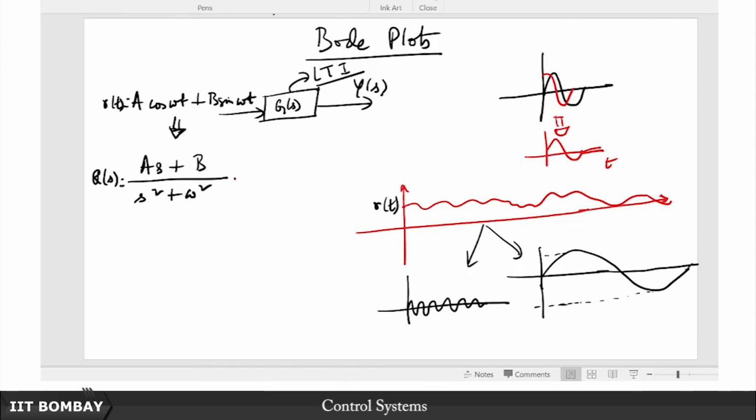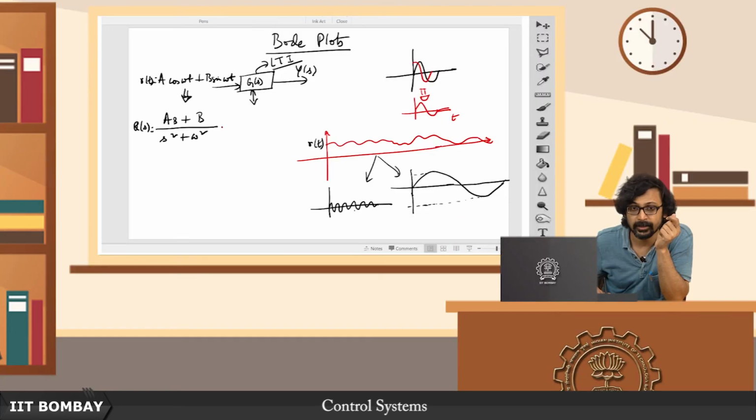So this is the frequency domain response, the frequency response. In every possible frequency that we might be interested in, how does this particular LTI system act on signals of different frequency?